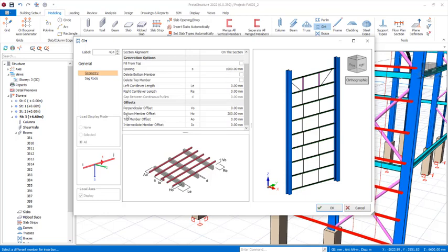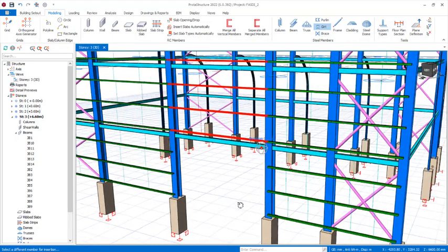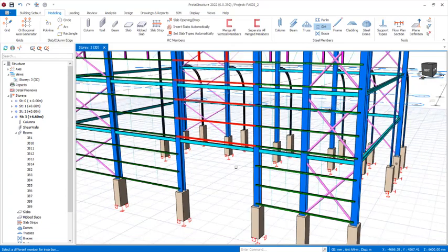and then come straight away to where you have some offset here. You can see bottom member offset is 200. So this place now you change it to 3200, just like this. So click on these provisions to have it shifted. You can see it's been shifted to this extent. Click on the OK option, so you can have this place open for the entrance door.